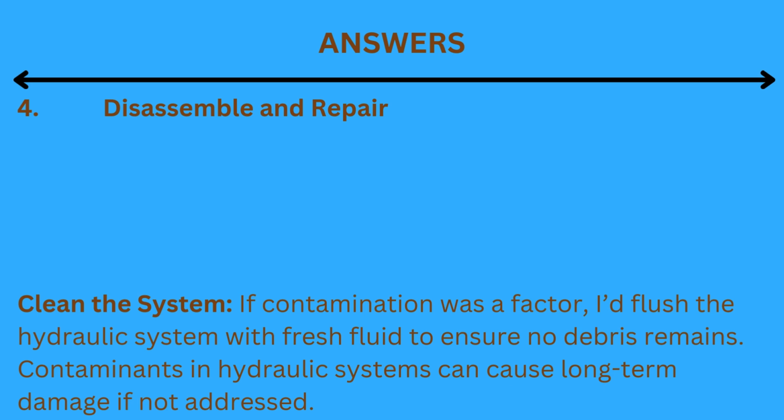If contamination was a factor, I'd flush the hydraulic system with fresh fluid to ensure no debris remains. Contaminants in hydraulic systems can cause long-term damage if not addressed.